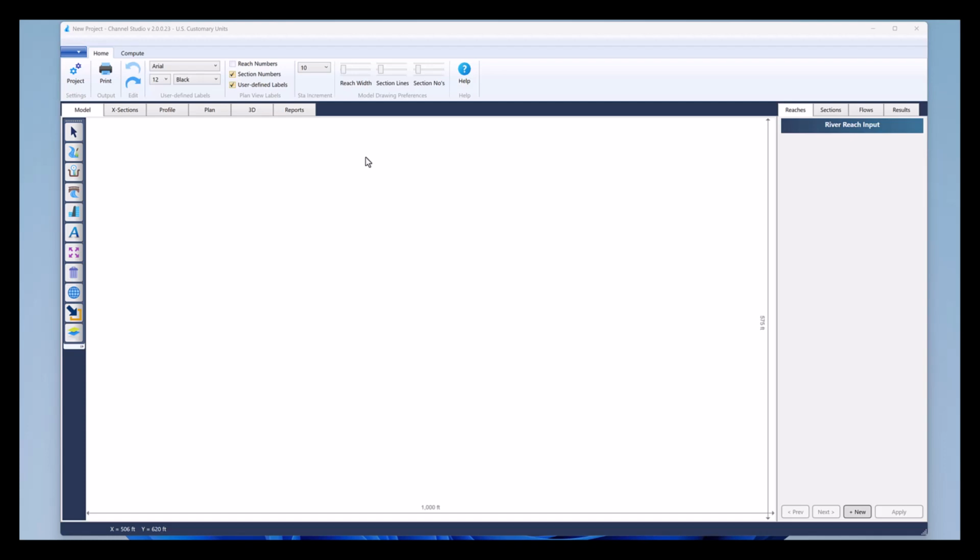system, which can include natural or man-made channels, bridges, culverts, and inline weirs. You can also add a background map to draw against from either an image file, a DXF, or LandXML files. You can also import a TIN surface from which you can cut cross sections. So as you're about to see, the user interface was designed to minimize inputs, eliminate messy dialog boxes, and put everything right in front of you.